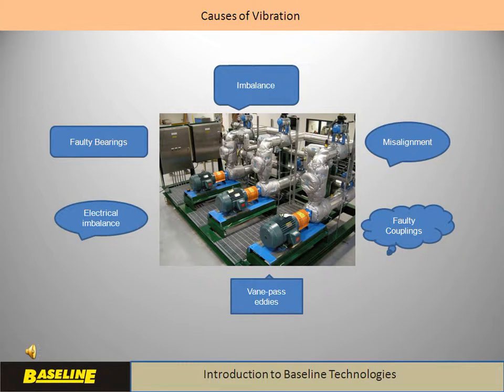Electrical motors may also exhibit vibrations due to an imbalanced or saturating stator field, which creates a distorted rotating field. Such vibration normally occurs at the electrical frequency or its odd harmonics. If the motor is also mechanically imbalanced, then the phenomenon of beats at the slip frequency is often observed.